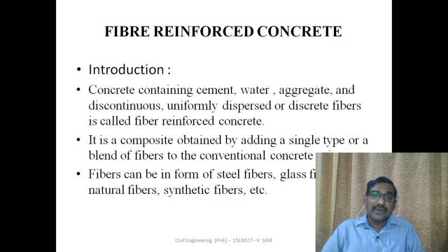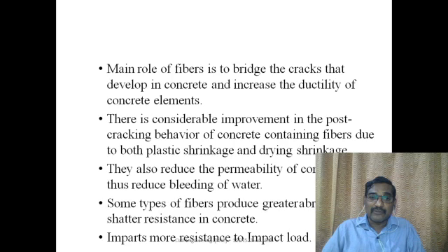Next is fiber reinforced concrete. As we know, concrete is very strong in compression and weak in tension. To make it strong in tension, we will reinforce with some additional fibers in the form of steel, glass, synthetic fibers, asbestos, etc. It is a composite material obtained by adding single type or blended of fibers in conventional concrete mix.